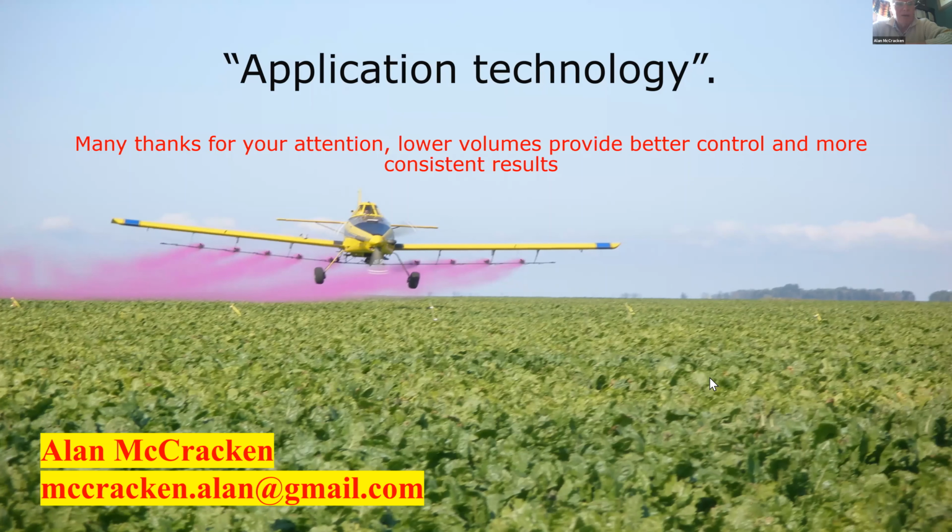You people being pilots, if you ever get called to spray locusts, first thing you have to learn is you have to fly high, because if a swarm of locusts goes in the air intake on your engine, you'll be on the ground quicker than you'd anticipated, because it'll choke your engine. So the aircraft has to fly high, 100 feet, 150 feet to be above the swarm. And we use the chemical as pure as possible, with almost no water.